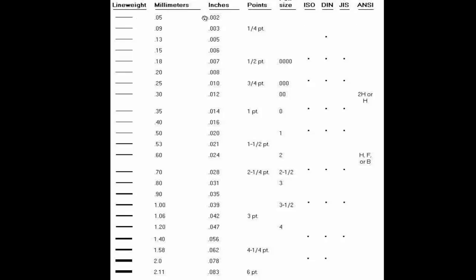And that's what we would use for what we call our construction lines or our temporary lines. As we get down here, the softer the lead, the more often you have to sharpen it, to keep your lead even on the paper. But you can see some of these line weights get pretty thick, and we'll utilize this on the computer to show definition and show the importance of objects. The thicker the line, the more it is on the plane of projection and visible.